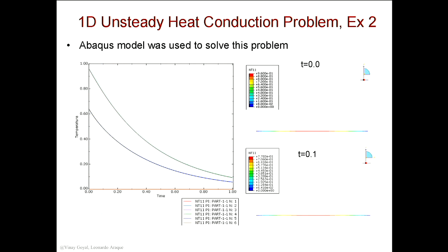So let's see. If I go here, 0.4. Sorry, what were we looking at, 0.1? 0.1. You know, it's not perfect. I was at 0.44. But you know what? I went 0.1 seconds. That's my time step. In Abaqus, I did 0.01, right? And I did forward difference, while in Abaqus, I was doing implicit, which is more accurate. So that's not too shabby.